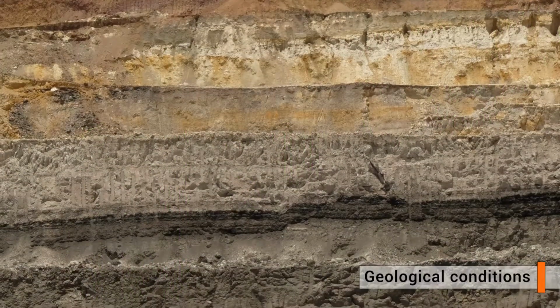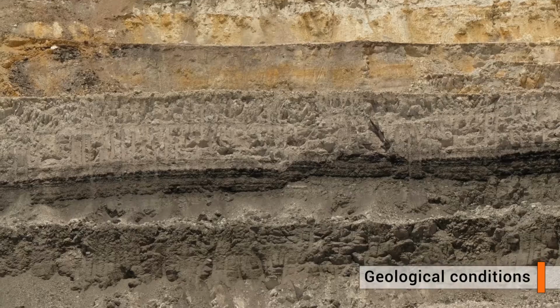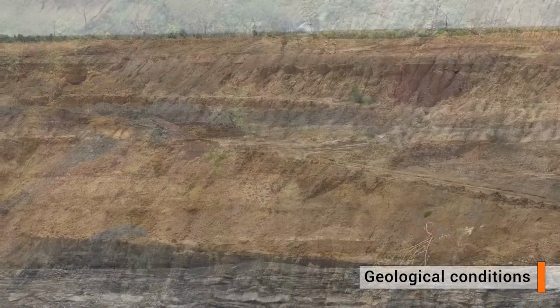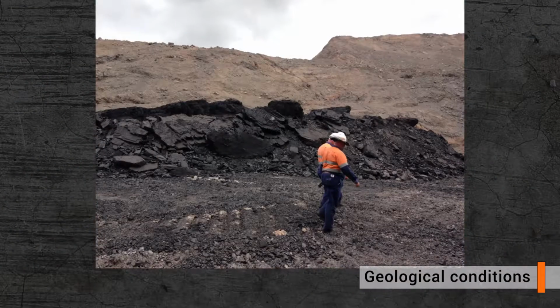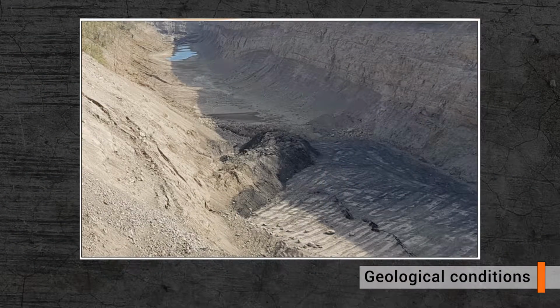Changes in rock type, for example, from competent sandstone to weak mudstone or coal. Persistent dikes or sills. Extensive zones of highly weathered rock or local rolling of generally horizontal strata, and weak floor conditions, particularly at the base of low walls or dumps.